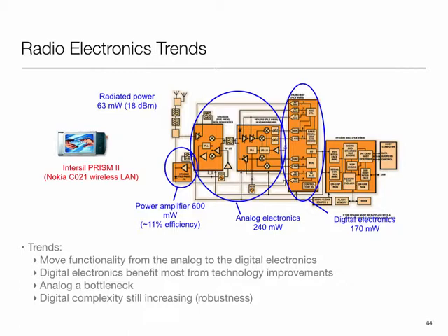So I can carry information which affects the amplitude. If information is carried in the amplitude of my signal, then I have to preserve that information, because otherwise a nonlinear system can create a lot of problems. Depending upon where the information is being carried, I may need a linear amplifier, or I may get away with a nonlinear amplifier. Now we can make a nonlinear amplifier extremely efficient, but linearity comes at a cost. So depending upon the type of modulation, namely where the information is being carried, whether in the phase, the amplitude or the frequency of the signal, it's going to affect how efficient an amplifier you have.